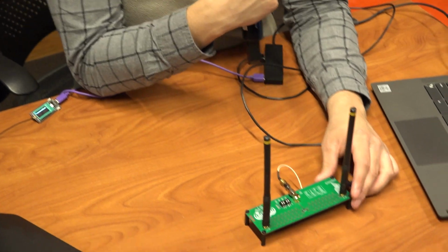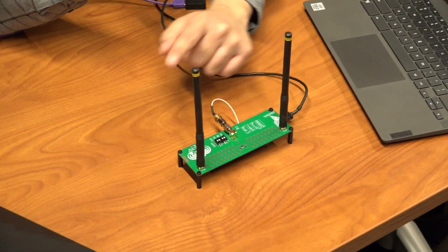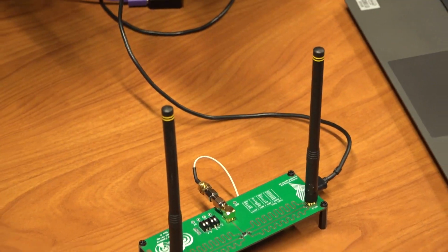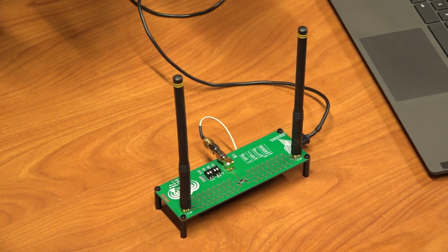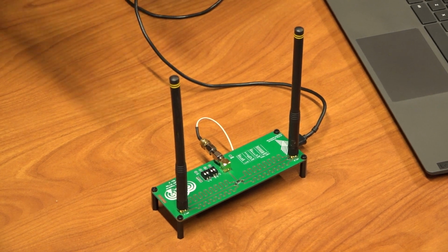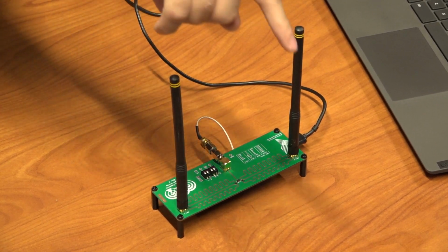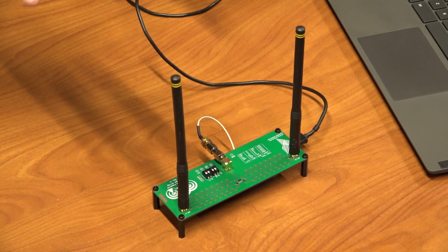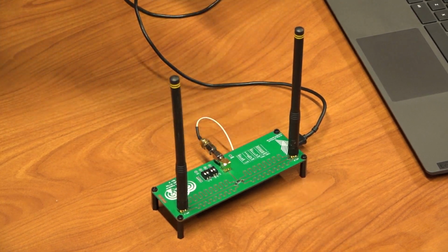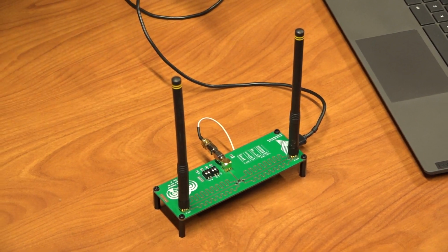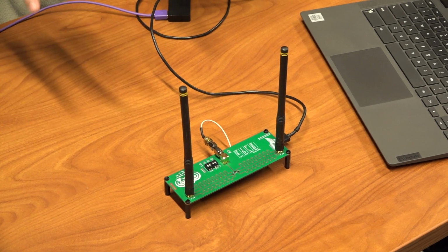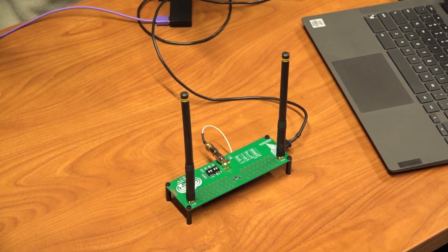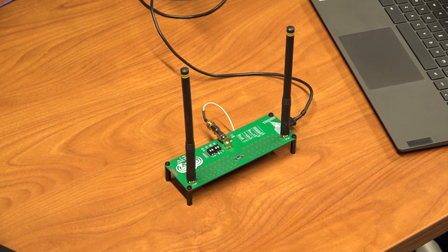The basic idea, as Zhuo said, is that we can introduce different phase shifts to each of these antennas and steer the main lobe of this device in a particular direction. So how we try to find the best nulling pattern is we essentially just cycle through all of the nulling patterns at first. We pick a nulling pattern, and we send a few packets just to see what each of the gateways is going to get. In particular, we're interested in the signal-to-noise ratio because we treat interference essentially the same as noise in the network when it comes to RF systems.